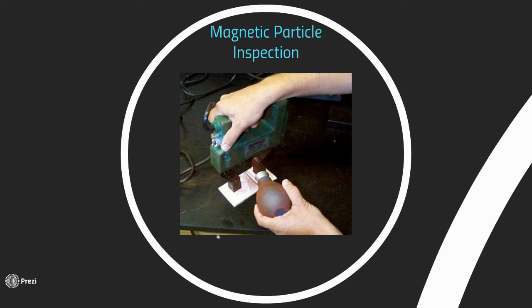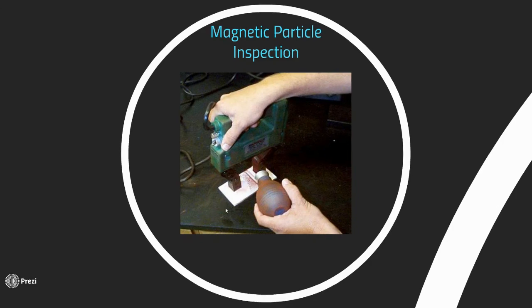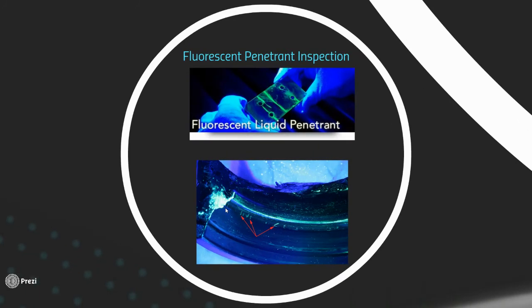And then it turns out that if you have any defects or cracks or voids, that disrupts the magnetic field, and you can see it, okay? With those iron filings, you can see the filings kind of stop and they have to go around, and that's where a crack or a void is. Now, magnetic particle inspection is only meant for a surface or just below the surface testing. It can't test for voids or cracks very deep within your product or your metal.